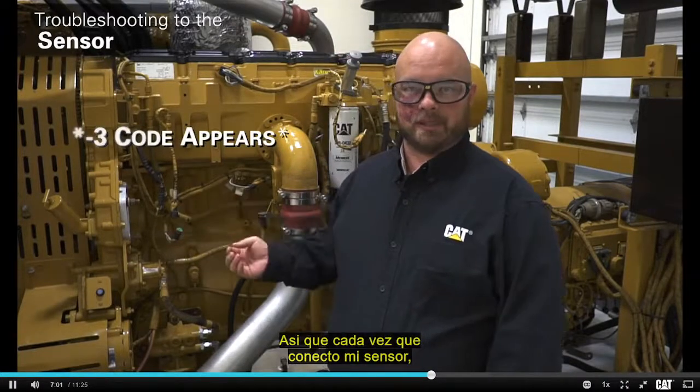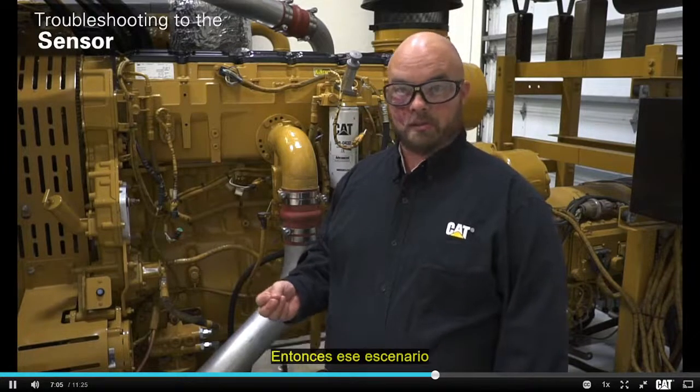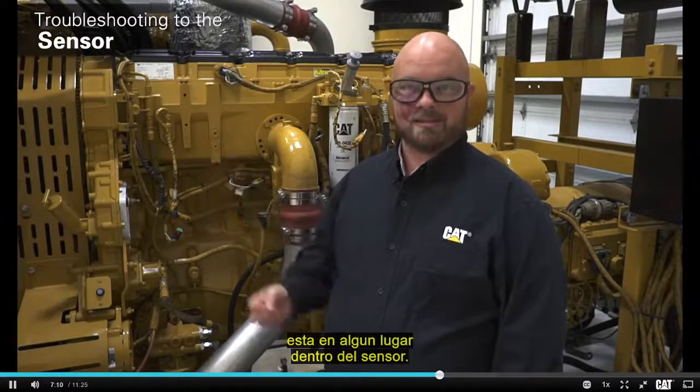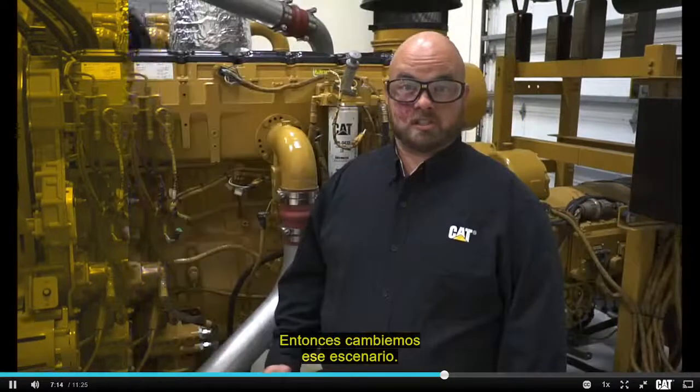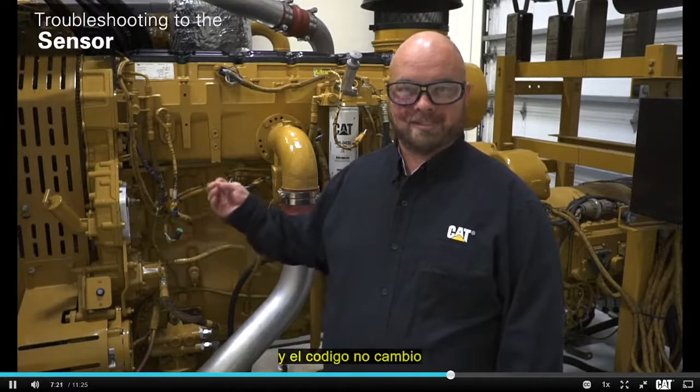So every time I plug in my sensor, I get a -4 voltage below normal code. That scenario would tell me that the short circuit I'm searching for is somewhere inside the sensor, and I go ahead and replace my sensor at this point. So let's change that scenario now. If we made our open circuit condition and we waited our debounce time,